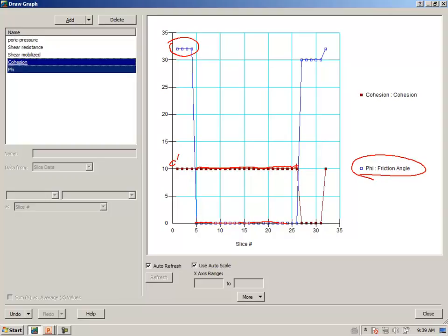Then as the slip surface comes out of the zone that has been marked yellow, we now have our frictional component again, and we have our conventional strength in this area here. But the point of interest is this zone here where the frictional component has dropped to 0, and all that we are left with is the undrained steady state strength.